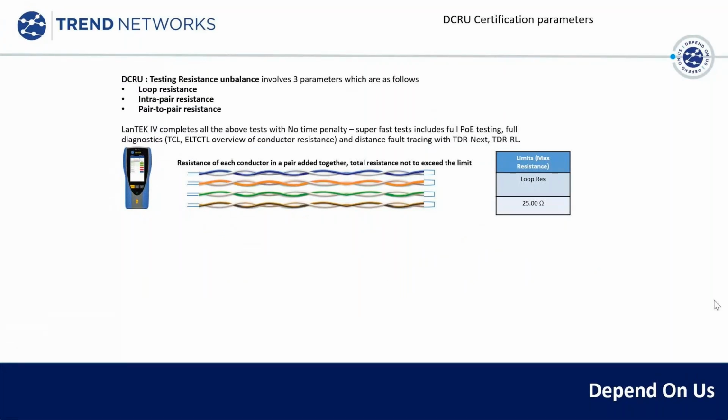So again, what is it? If you can remember, I talked about the cable pairs. We're going to do three parts of those cable pairs, and I mentioned the twist rates. So on screen now I've got some of the twists, some of the pairs, and we'll talk about standard loop resistance. So what we're looking at really is each individual pair pretty much looped back. So I've got on one side the tester, just from one end, it's just going to look at the resistance across that cable per pair.